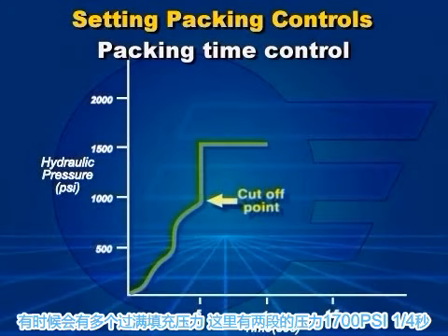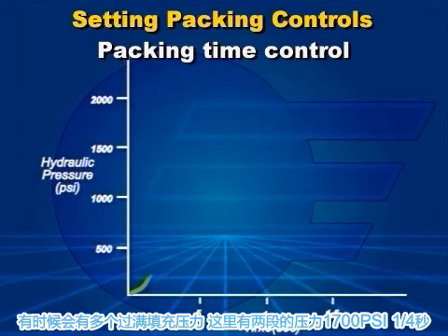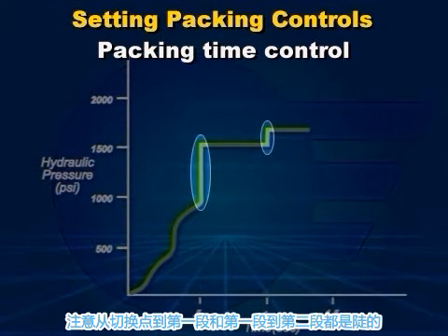Sometimes more than one packing pressure is used. Here we've added a second packing pressure of 1700 psi for 1/4 of a second. Note that the transition from the cutoff point to the first pressure setting, and from the first pressure setting to the second pressure setting, is abrupt.